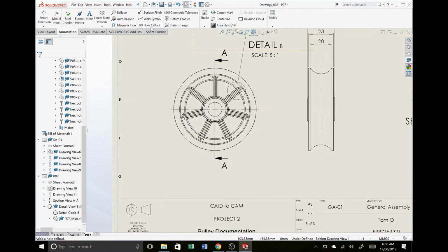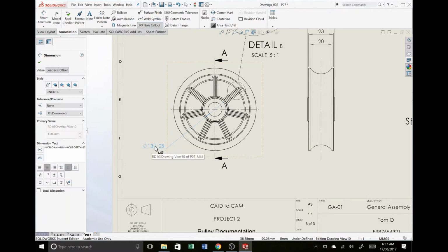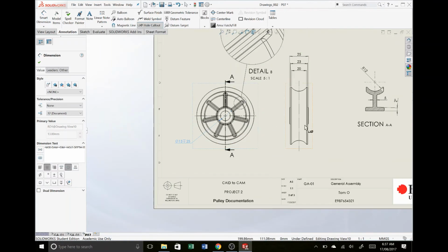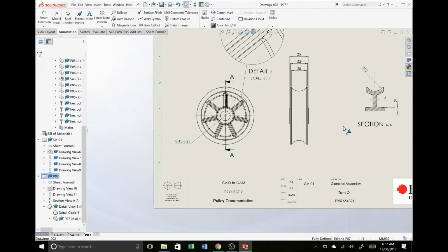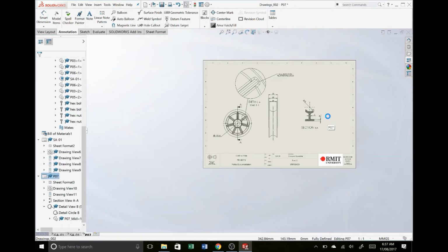All right. And finally, if you've used a sheet metal part, or if you've got any hole, you could use the hole callout to dimension that hole, and that will give us a little bit more information than normal. For example, this is telling us that it's a 13mm diameter hole that is drilled 25mm deep. We know it's 25mm because that's the depth of the aluminium there, or acetyl nylon in this case. Very good. So that should be a pretty nice kind of overview for you.